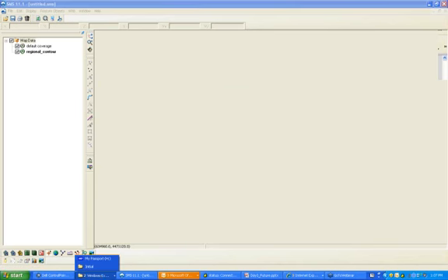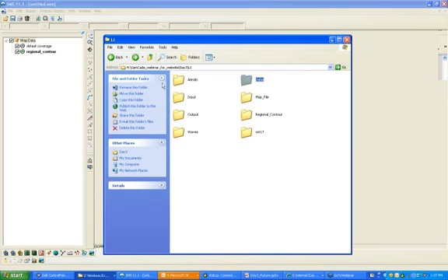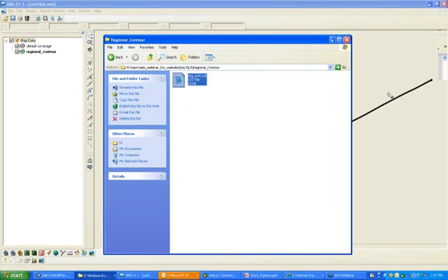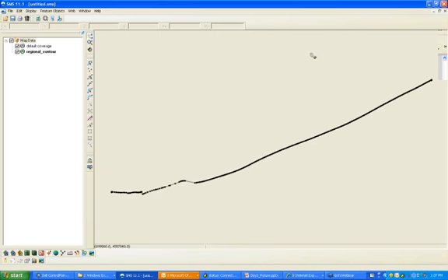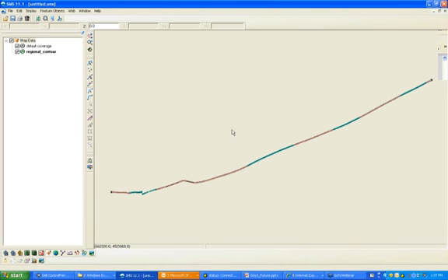We're going to go back to all of our files. And Gencade, in this Long Island case, I have the regional contour in this folder. I'm going to open it up and bring it into Gencade. So again, it comes in as a generic arc. We're going to click on Select Feature Arc, and we're going to double click, and then we're going to go to Regional Contour and click OK.